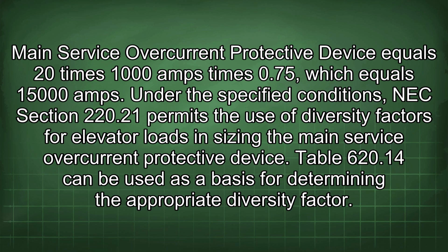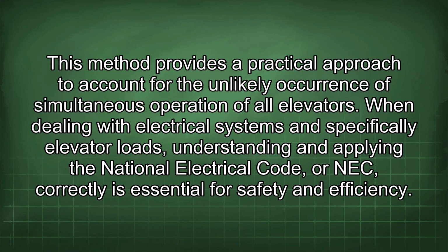Under the specified conditions, NEC Section 220.21 permits the use of diversity factors for elevator loads and sizing the main service overcurrent protective device. Table 620.14 can be used as a basis for determining the appropriate diversity factor. This method provides a practical approach to account for the unlikely occurrence of simultaneous operation of all elevators.